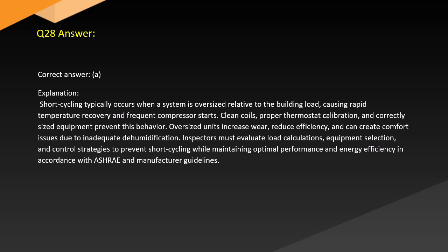Inspectors must evaluate load calculations, equipment selection, and control strategies to prevent short cycling while maintaining optimal performance and energy efficiency in accordance with ASHRAE and manufacturer guidelines.